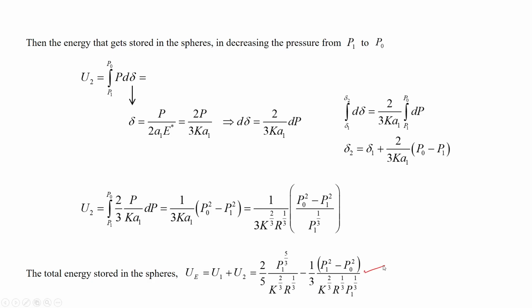So, this is this. Remember that here P0 square minus P1 square, and so you can take this minus out. So, this quantity P1 is actually larger than P0, so this quantity is actually positive. In essence, what it means is that in the Hertz contact pressure you gave some extra amount of energy, and that you subtracted during the work that is done by this adhesion force. That is how it has to be interpreted. So, in any case this is the expression of the total energy.